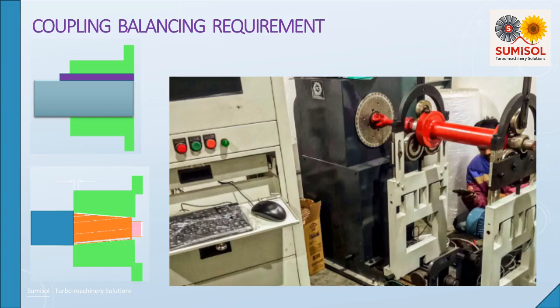For this, the coupling subassembly or the coupling component is drawn onto a fixture shaft and balanced with a filled keyway. The keyway can either be filled with a half-key or the coupling is balanced prior to keywaying. The latter is the more common and easier method because the exact location and weight of the key must be known when balancing with an inserted half-key is performed.